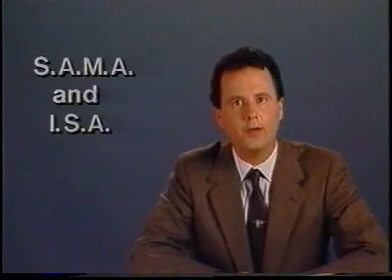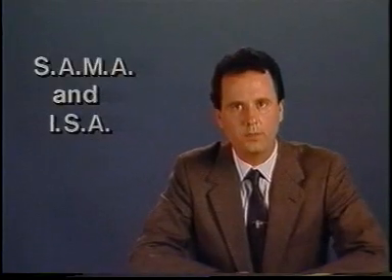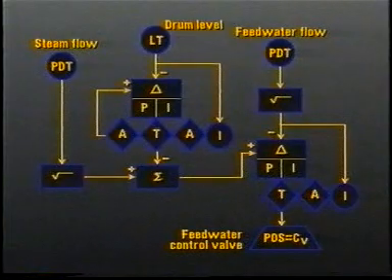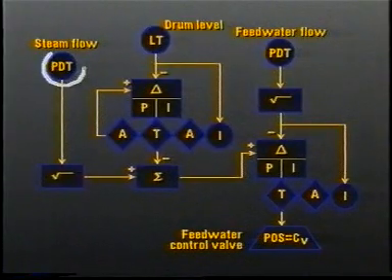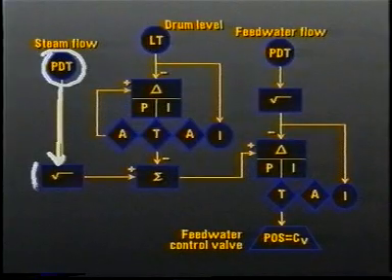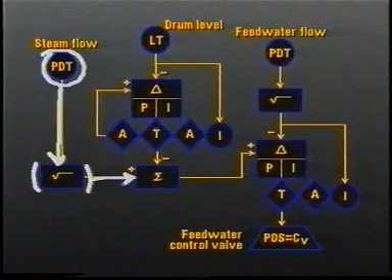When more complicated diagramming is required, ISA and SAMA diagramming are often used together in order to provide a complete picture of the hardware and its function. In this example of a three-element feed water control, we see that on the steam flow side, a differential pressure transmitter feeds a signal to an automatic signal processor, which in turn feeds a square root signal to a summing